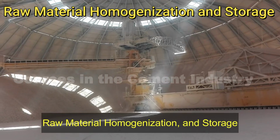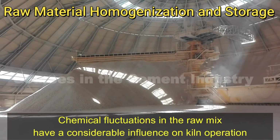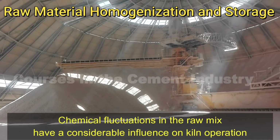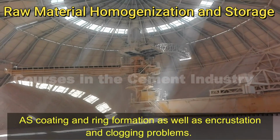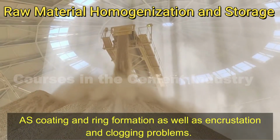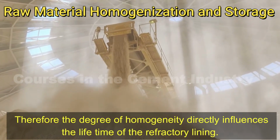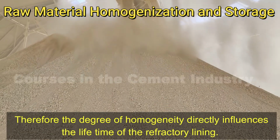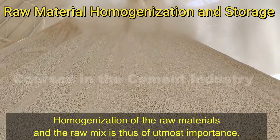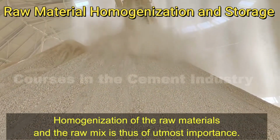Raw material homogenization and storage. Chemical fluctuations in the raw mix have a considerable influence on kiln operation, as well as coating and ring formation, incrustation, and clogging problems. Therefore, the degree of homogeneity directly influences the lifetime of the refractory lining. Homogenization of the raw materials and the raw mix is thus of utmost importance.